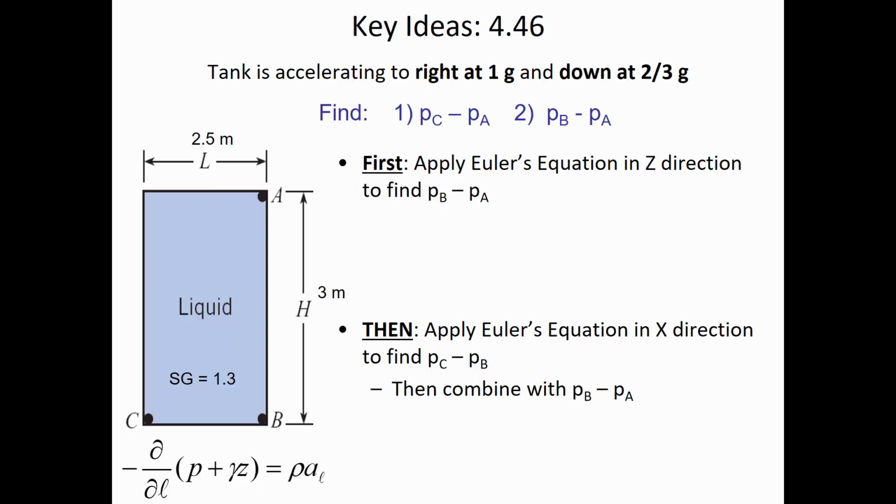When you're finding Z1 and Z2, you could have said, let's have the vertical datum be at the top of this tank. So when I'm working vertically, I could say ZA is 0 and ZB is -3. And you'd still get the same numbers that way. Any other questions?